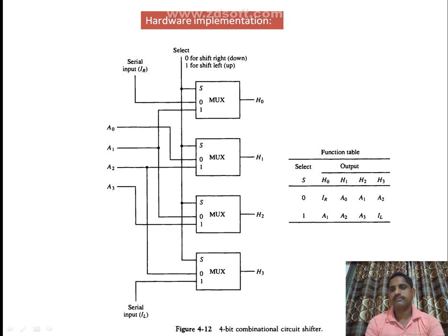In the hardware implementation, a possible choice for the shift unit would be a bidirectional shift register with parallel load. Information can be transferred to the register in parallel, and the register can perform the operations in this configuration. In this type of configuration, one clock pulse is needed for loading the data into the register, and another pulse is needed for loading the processor registers. This is more efficient for the particular instructions implemented for the shift operation.